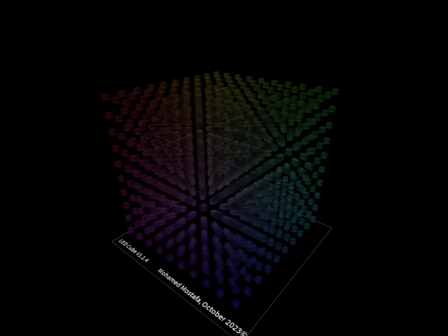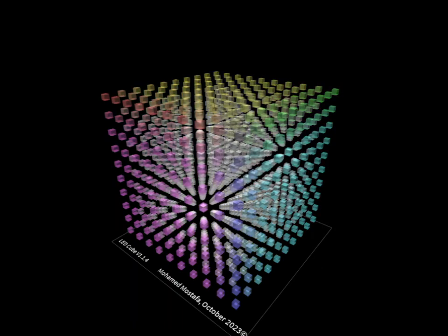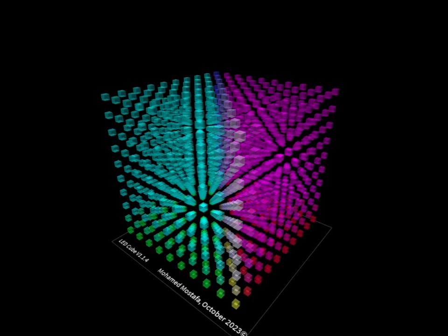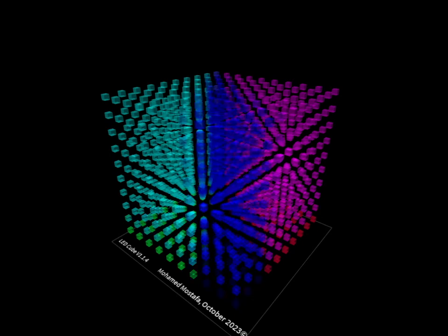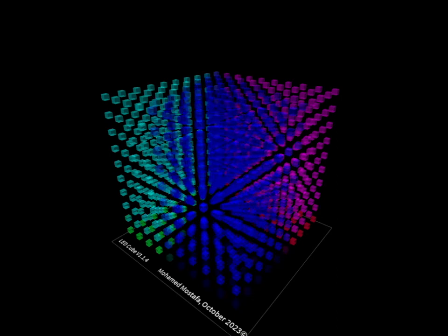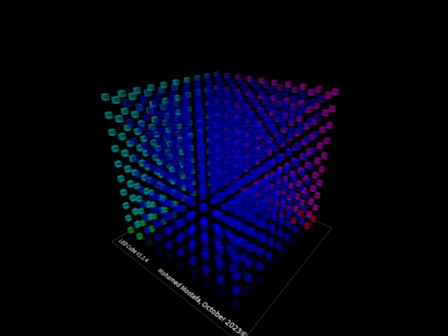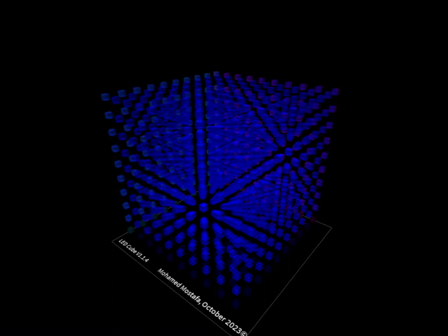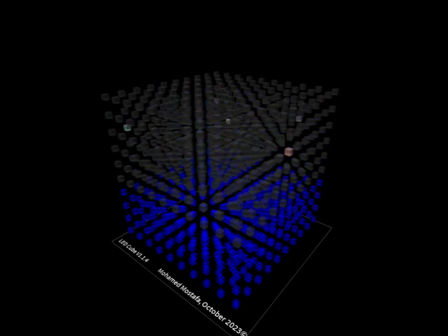For an 8x8x8 LED cube with only 10 mA per LED, you need to switch 0.64 ampere. See Table 2 for an overview of power requirements for an LED layer of different sizes. This table shows the current draw with all LEDs on. If you are planning to build a larger cube than 8x8x8, or running each LED at more than 10-ish mA, remember to take into consideration that your layer transistors must be able to handle that load.